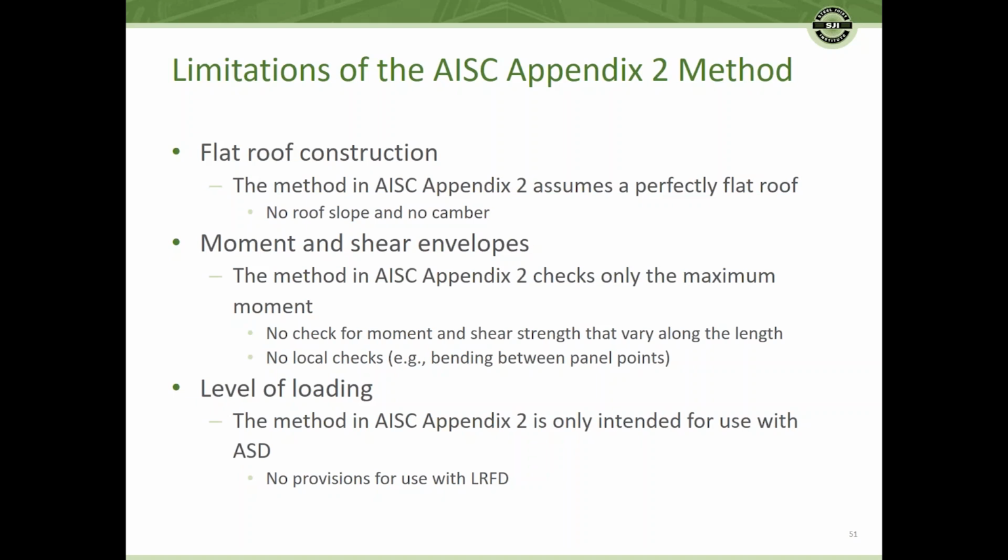Typical design for stability accounts for geometric nonlinearities, P delta effects, and material nonlinearities, such as inelasticity caused by yielding. Ponding, the reason it's different is that the nonlinearity is in the applied load. But there's no reason we can't treat this nonlinearity in the load the same way as we treat these other